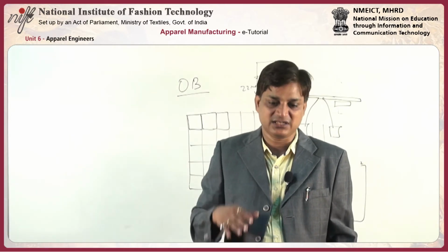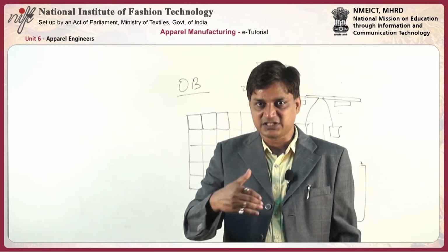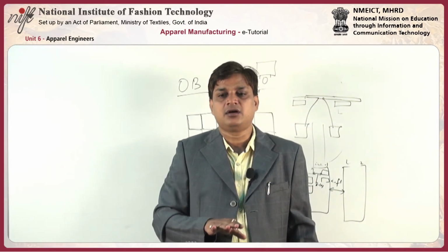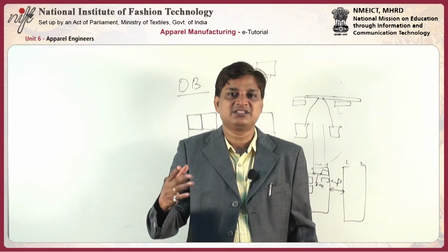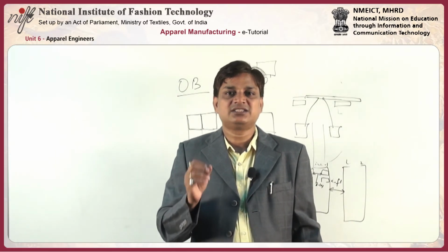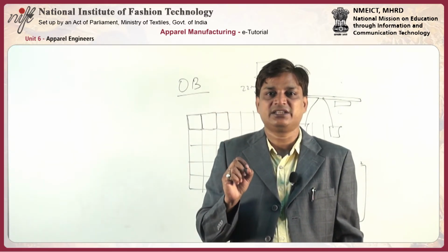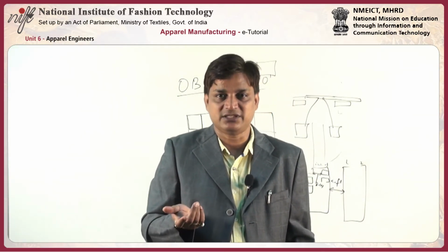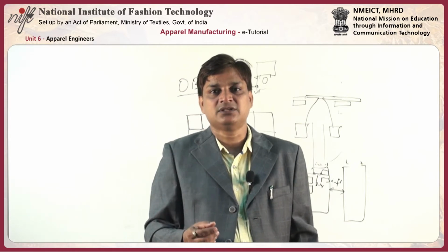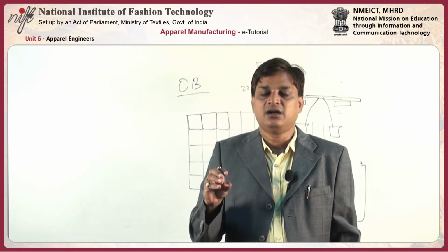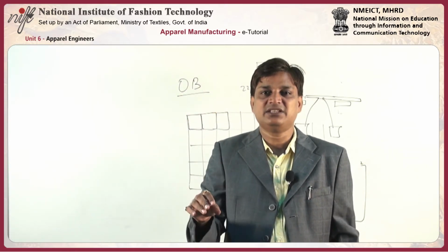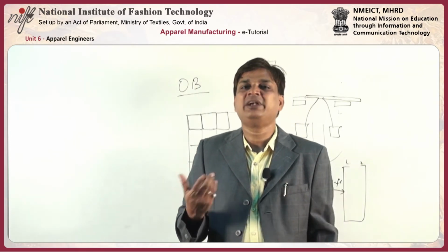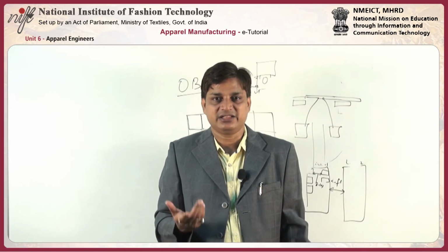But one problem is there. If you are keeping the bus bar underground, maybe due to some water seepage, or if we are doing the mopping inside the factory, there are chances like that. If a hole has been created, then there are chances the bus bar will get damaged, or the system will get damaged. Or in case any damage happens, then we have to take it out from underground. So maintenance will be difficult in that particular case.